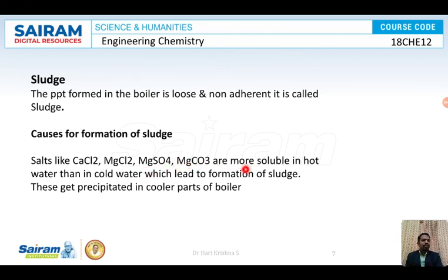These are not soluble in hot conditions. You might think it will only float, right? In a hotter condition, this precipitate will float. In a colder condition, what will happen? It will precipitate and choke. When water or steam is flowing from the source to the end, it will have many turnings. The temperature will not be even. When the temperature decreases, the sludge will precipitate.